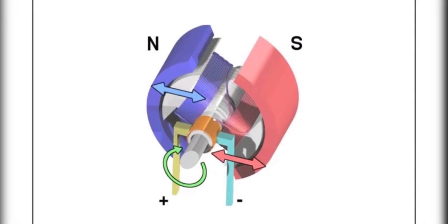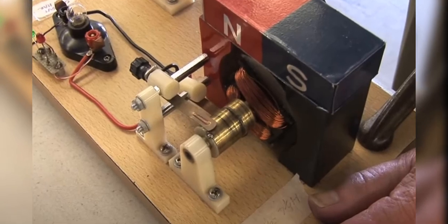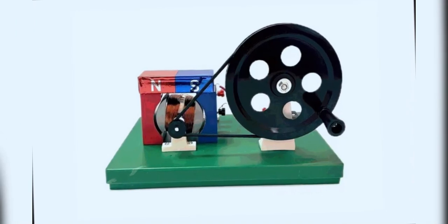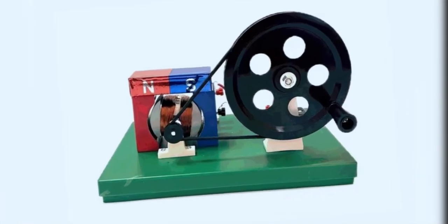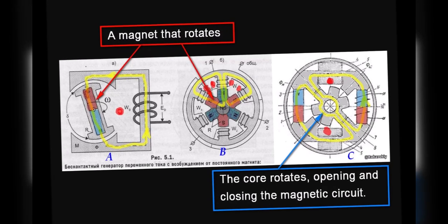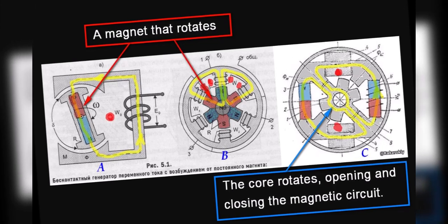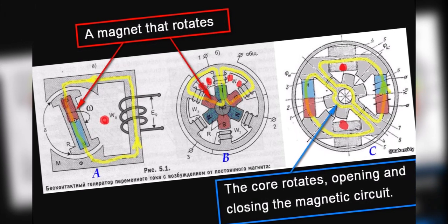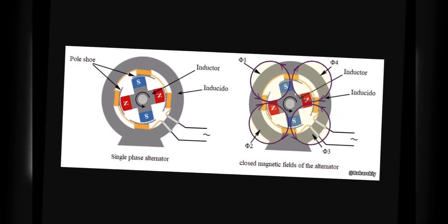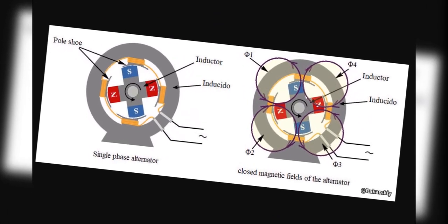Earlier I showed a handheld electromagnetic generator with a movable anchor, which is used for demonstration purposes. The anchor of the generator has a winding to create EMF and is used in two positions, as an alternating current generator and as a dynamo machine. This type of generator is related to the simplest electromagnetic generators with cores. In textbooks about typical synchronous generators, this particular version of the magnetic system is given, only with a rotating magnetic rotor. In these generators, the electromotive force is calculated using the transformer formula of EMF.